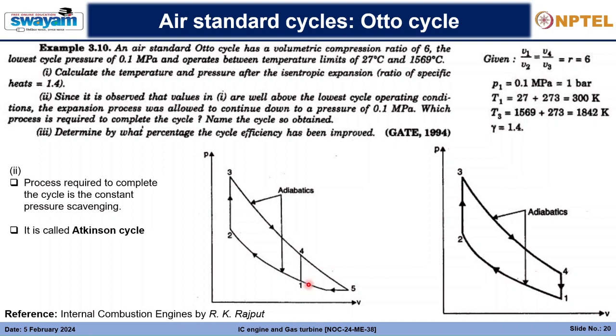Now there is a slight problem in this figure. Point 1 is having a pressure of around 0.1 megapascal, and point 5 is also after expansion till 0.1 megapascal. So these are lying on the same line actually, although the figure has a certain mistake out here.